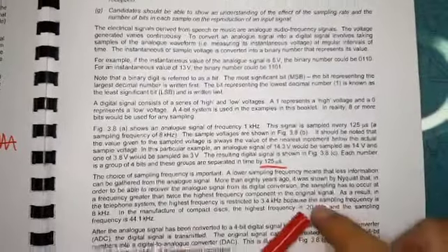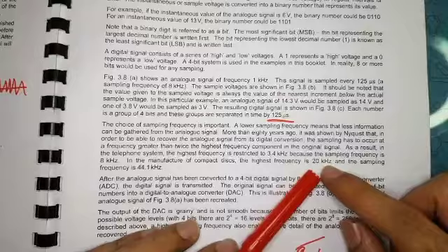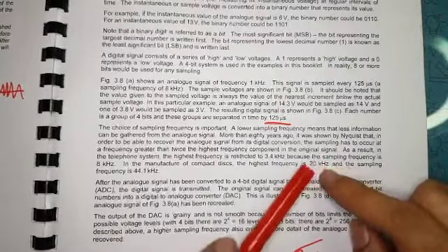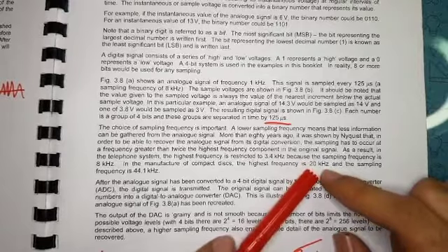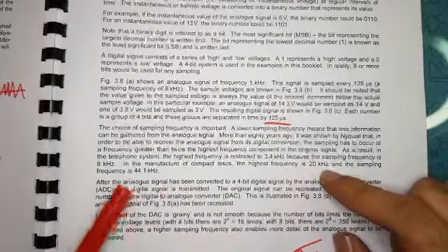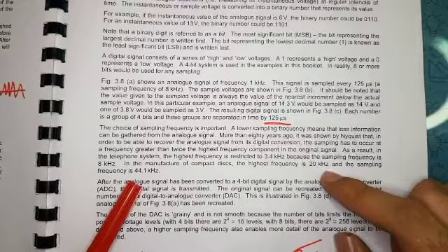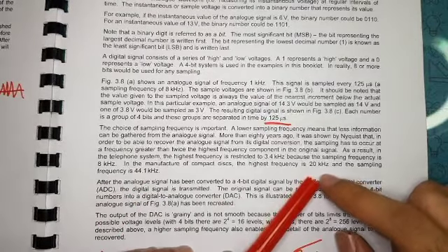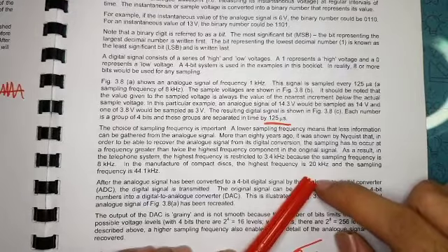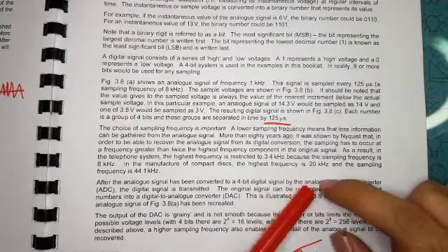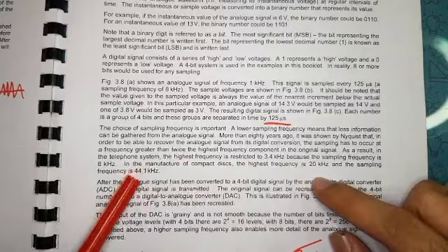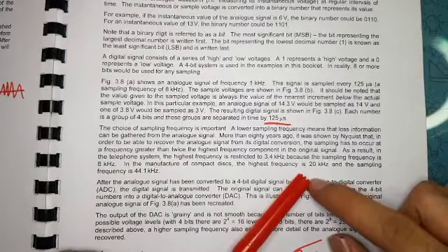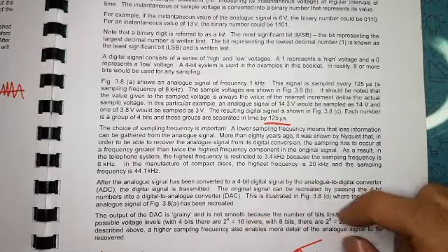But an important thing is, if you want to sample something at 20 kilohertz, you need to take something a little more than double. So if you're sampling a signal which has a highest frequency of 20 kilohertz, you should sample at a rate above 44.1 kilohertz, so that you can pick up the signal properly. There's a lot of detail in that, but I'm not going to go into it, because what you need to know is the sampling frequency has to be higher than double the frequency that you want to capture. Right, so that's that.